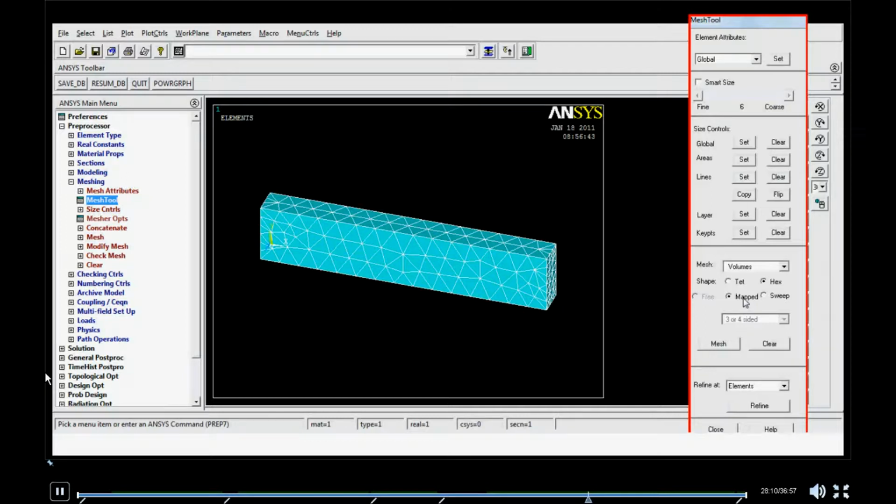Now whatever we are doing is automatic meshing, not manual. I mean, it is doing it automatically. It is deciding what the number of elements is, what the element edge length is, or the number of elements to be created. The user is not controlling here, or I am not controlling here how it should be, whether it is a tet or hex. Or I can control this to some extent.